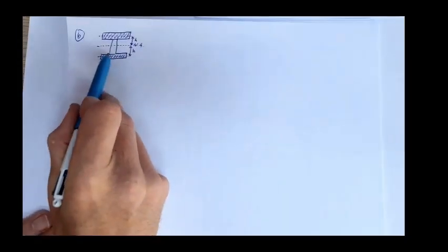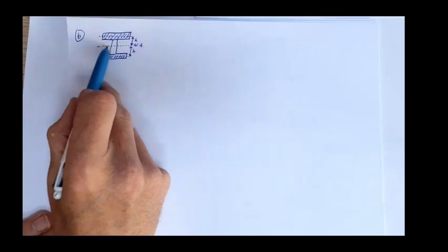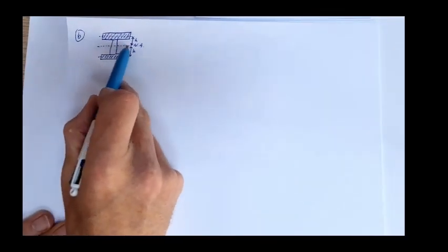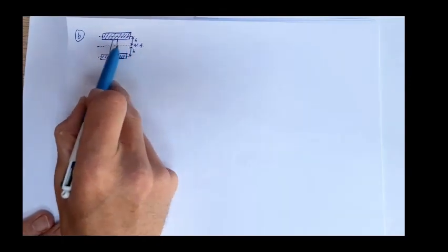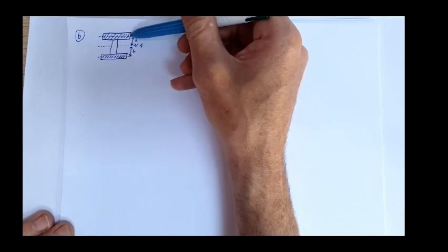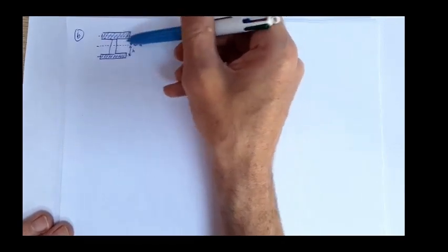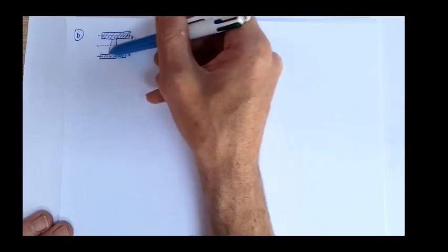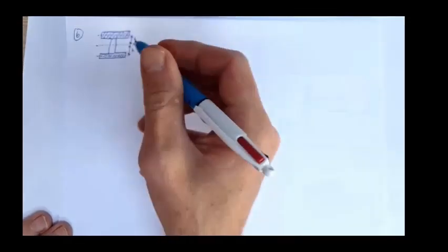And then we've got this rectangle in the middle, and the local neutral axis for that rectangle goes through the same axis as the global neutral axis for the shape. So we're going to have to shift the second moment of area of the top rectangle and the bottom rectangle, and the one in the middle we're not going to need to change.